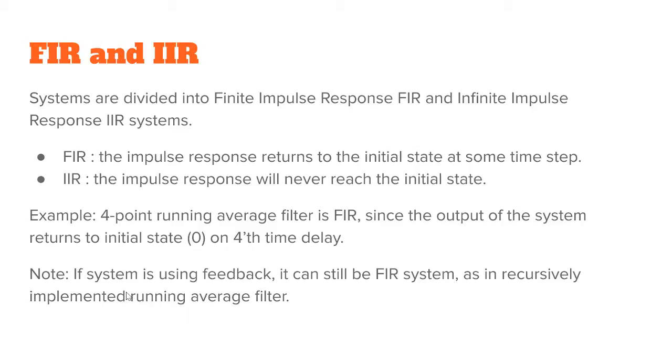And then we have this previous value of output. And here we have the sum, something like this. So it has a feedback element right here. That's the feedback when we take part of the output and put it back to the input, the same way as you would do on the feedback on the analog system.